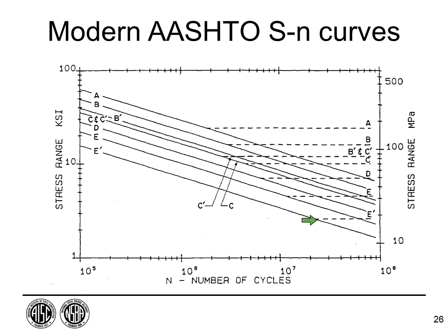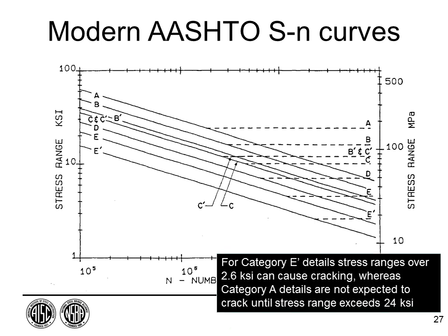That means that I would need to keep my stress ranges below 2.6 ksi to ensure I don't have any cracking. So that's quite low. Comparing it to E and A, it's almost an order of magnitude, isn't it? 2.6 times 10 would be 26, so it's very close to an order of magnitude. So quite a bit of range of different details.